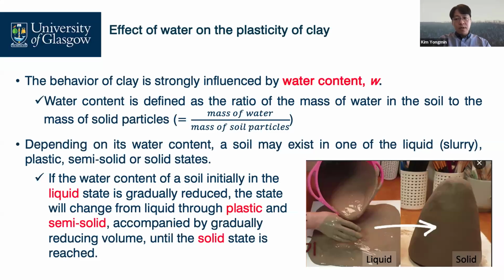The Atterberg limit is kind of water content. This water content governs the clay mineral behavior in terms of mechanical behavior and hydraulic behaviors. How do we define the water content in soils? It is the ratio of the mass of water in the soil to the mass of solid particles.